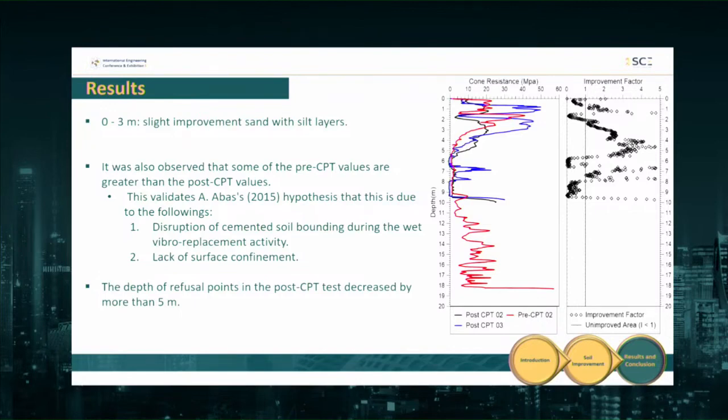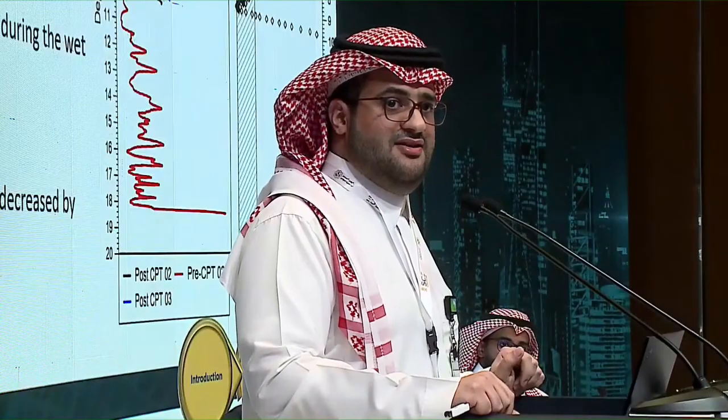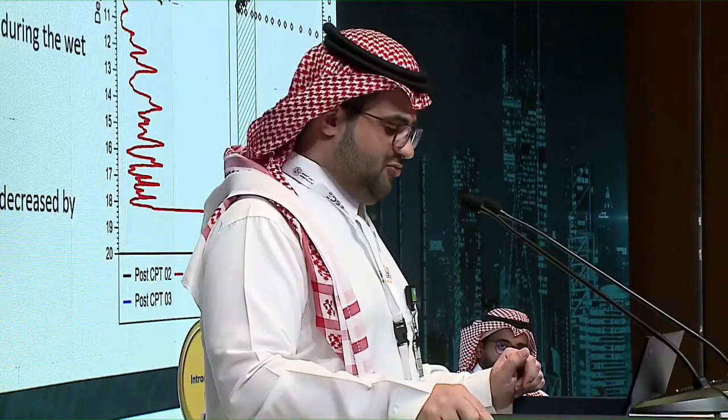It was observed that some of the pre-cone penetration test values are greater than the post ones, which should not be the case. However, this, I call it noise in the data, has been explained by Dr. Abbas' hypothesis in 2015, that this is due to a disruption of the cemented soil bonding during the wet vibro replacement activities, also the lack of surface confinement. However, the depth of the refusal point in the post-CPT test decreased by more than 5 meters, which is a good indication.